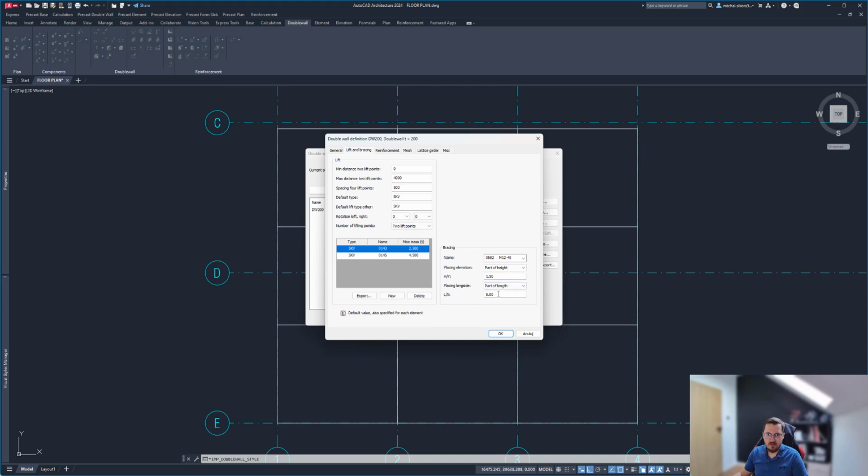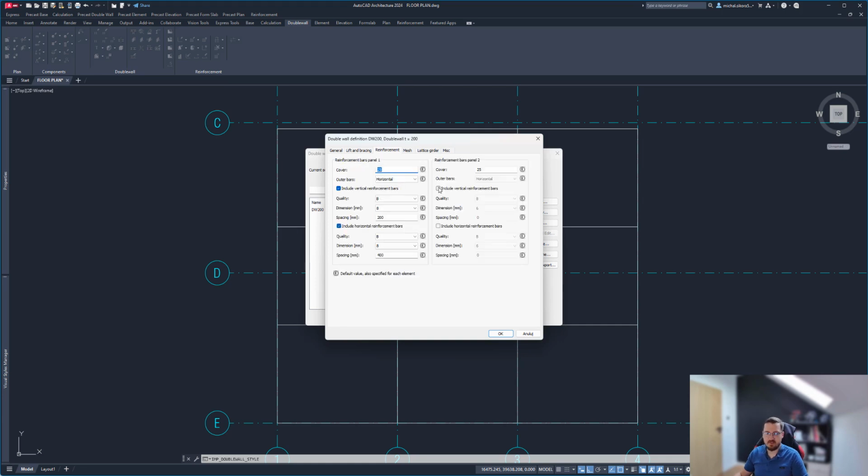And you also specify the placement along the length of that, and the type of the bracing point in a wall that's available to you. That's also here. The next step allows you to specify the reinforcement for the panels. So the reinforcement tab is about loose bar reinforcement.